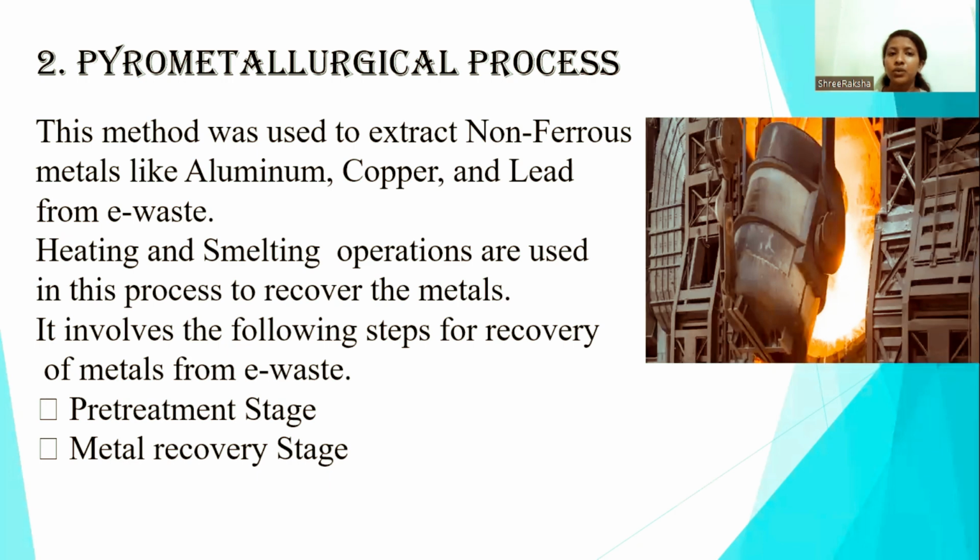Next step is the pyrometallurgical process. This process is used to extract non-ferrous metals like aluminium, copper, and lead from the e-waste. Heating and smelting operations are used in this process to recover the metals. It involves the following steps, that is pre-treatment stage and metal recovery stage.